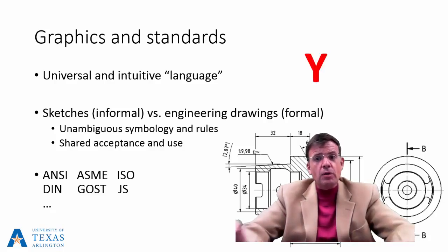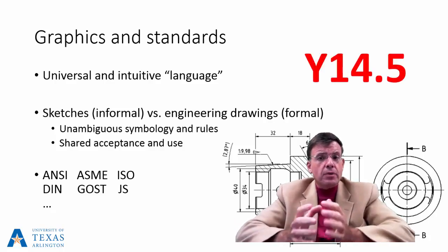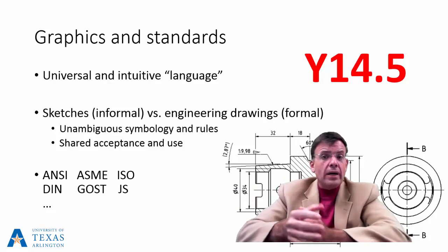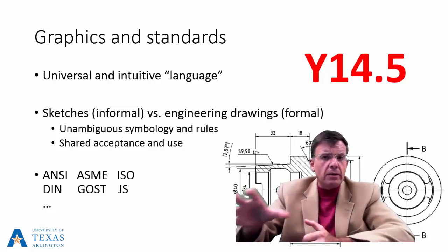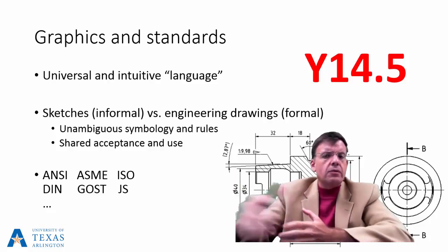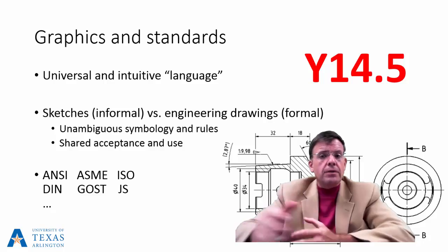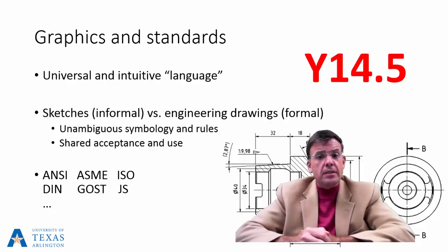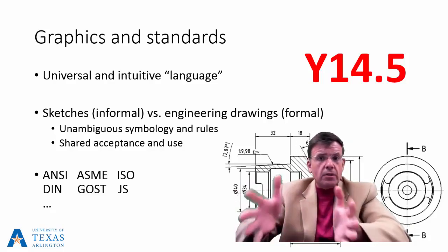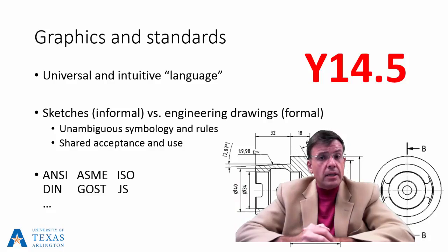Okay, and that's something that will be very relevant and important here in the course. We will be following ASME/ANSI Y14 standards, specifically Y14.5. That's one of the biggies there, and then there's another one, Y14.41, that deals with a so-called model-based definition. And no, of course, ANSI and ASME are not the only ones. Those dominate here in the United States.